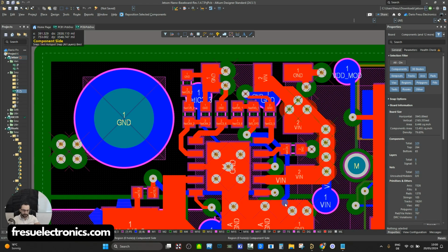Okay, so we mentioned that these transient currents are generated by the logic gates during the switching time, going from the low state to the high state or vice versa, from the high state to the low state. This is important because it means that we cannot really have an impact on the timing of the switching, because otherwise we are going to reduce the performance of these logic gates. What we actually want to do is to create a perfect environment for the power delivery network so that we can bring this transient current when it is most needed.